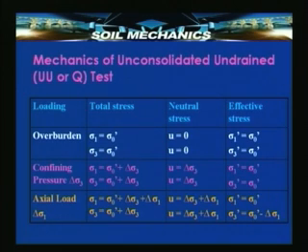It will obviously be the stress under which the soil has been formed, that is the overburden stress, pre-existing stress on the soil before the test, before the specimen is extracted and the test is conducted. And therefore, in this case, in order to know the stress state at the end of the test, we have got to take the initial overburden effective stress that was present in the soil before the test was conducted.